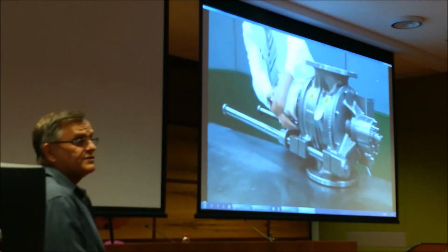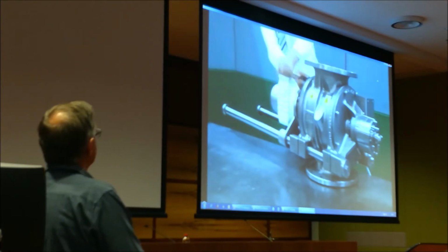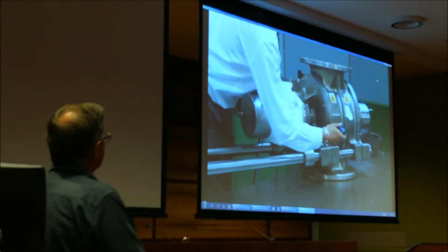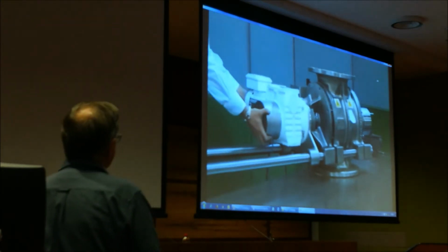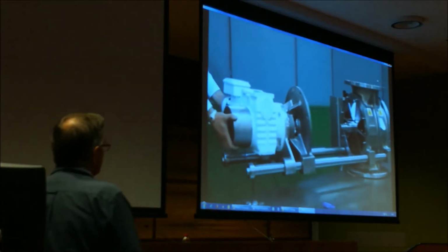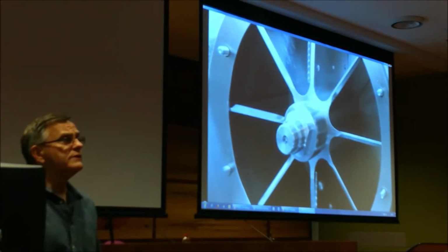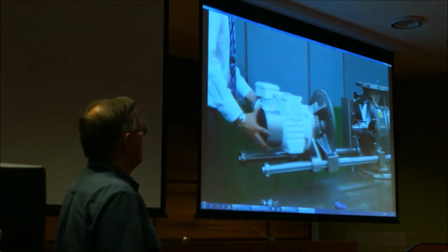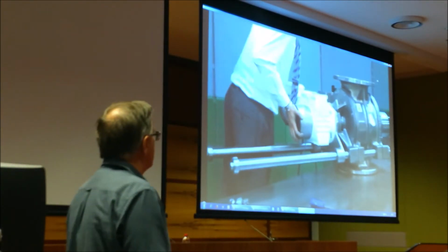And you can also do the same on the other end, the drive end. And this is also a drop-through rotary valve. And there, this is what we call an open rotor, so there's no end plate on the rotor. You can also buy a closed rotor that's got a closed plate on there. So different valves for different applications, different products.